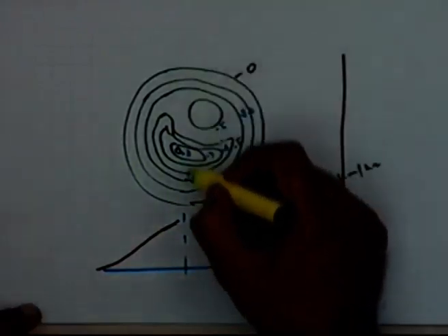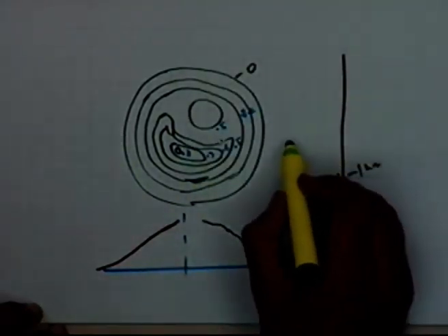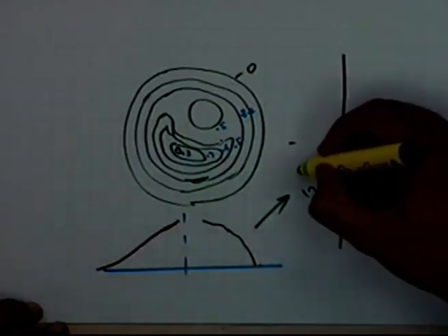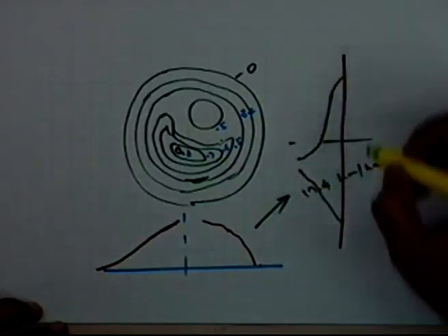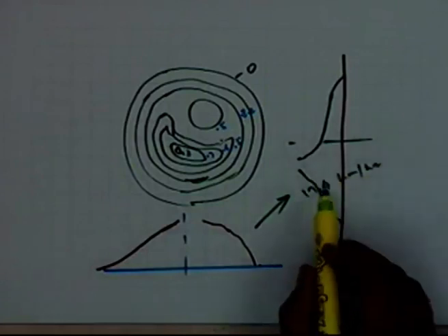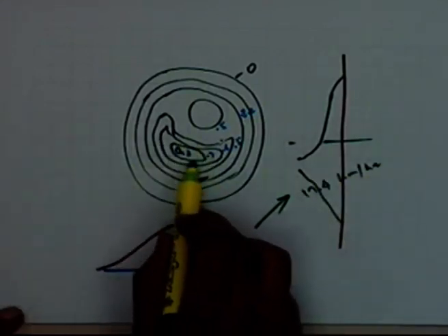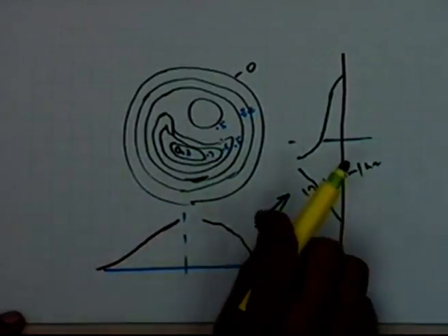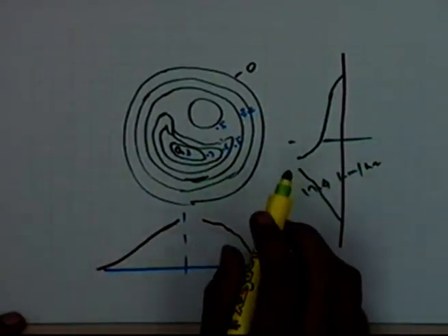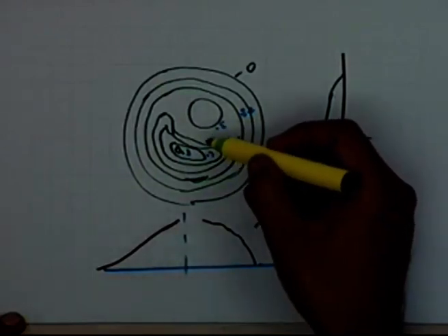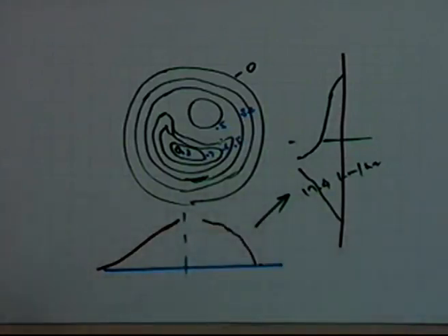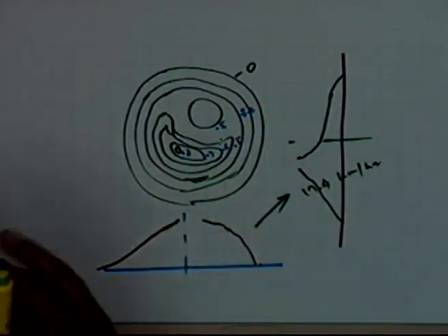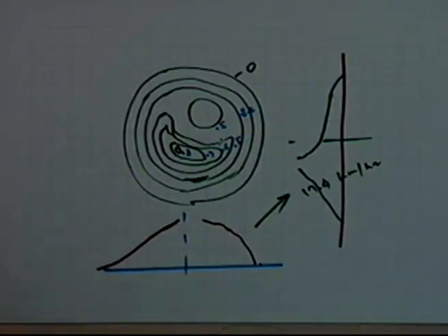If I take the section here, the distribution pattern will be somewhat of this nature. So you will find that most of the water has deposited in this area because the wind was blowing in this direction. And this distortion in the distribution pattern will create a lot of undulations in the application depth which you intend to apply.